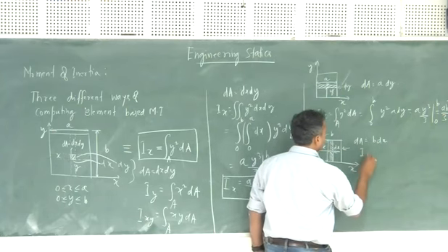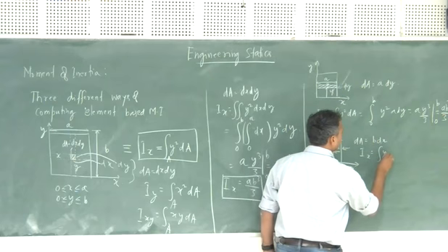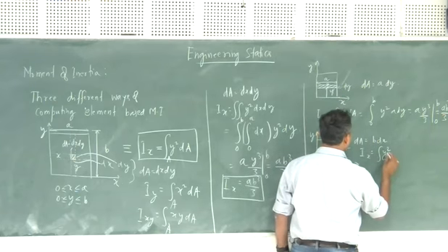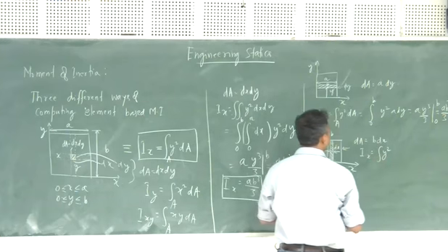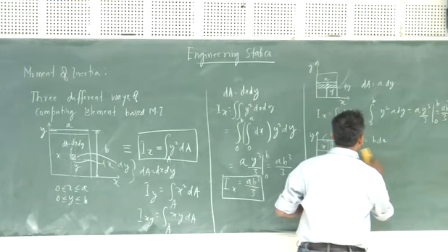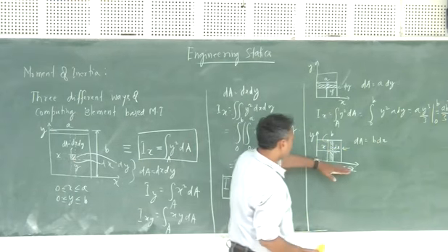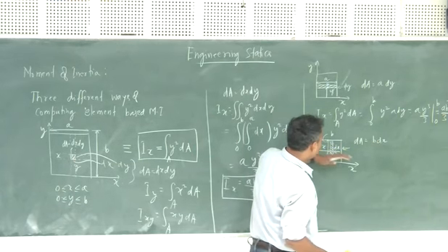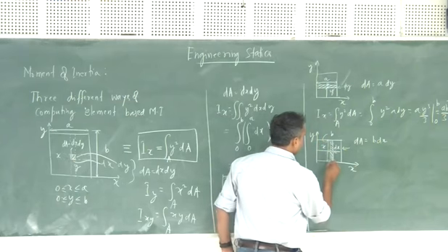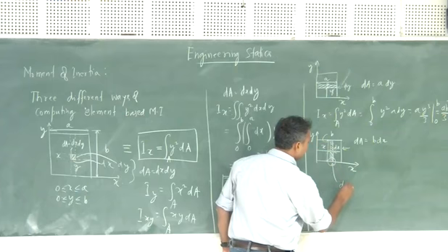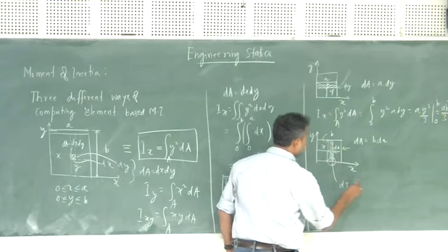So how will you define your Ix? Ix is the integral of y squared dA. Since you have to find it about the x-axis, what will be dIx?